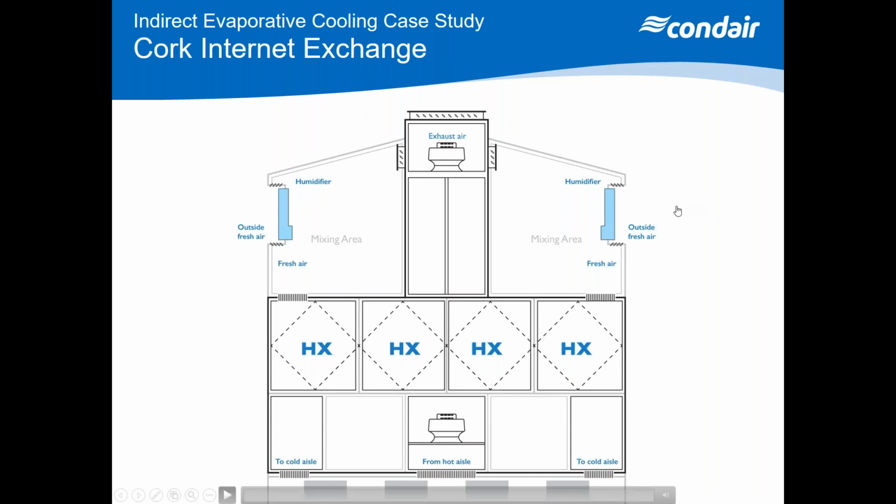And the same is happening on the other side. Air is coming through the evaporative cooler, is mixing, or indeed not mixing, depending on whether the controls are calling for that, goes through a damper and then goes through the first right-hand heat exchanger, and then goes through the second right-hand heat exchanger, and then goes up and is either exhausted or mixed. So you've got these 2 constant circulating systems. Same on this side, coming in, cooled, going over those heat exchangers and exhausted. In, cooled, cooled again, and then exhausted.